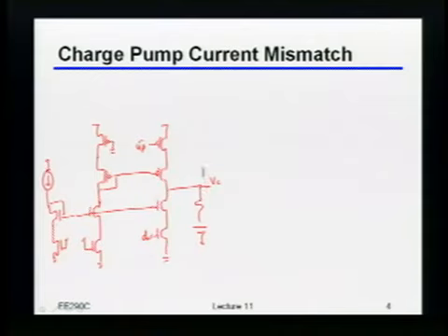So as an example, what might be the range of voltage that you'd like to support on that control voltage? And let's just assume that we had something like, I don't know, let's say a 1 volt supply, okay? So what do you think would be a nice range of voltage for you to cover at that output there? Roughly speaking, what do you think is feasible? 2V star to VDD minus 2V star.